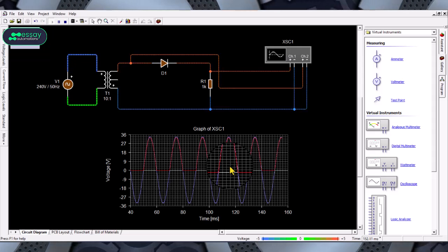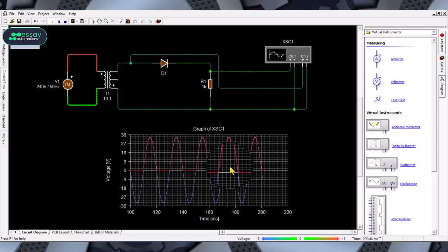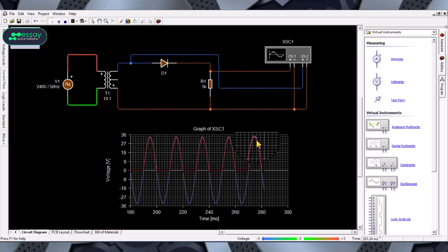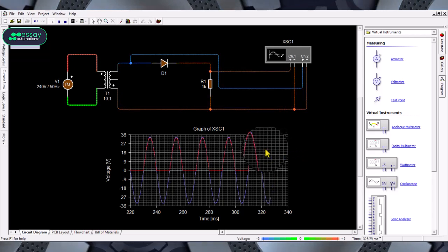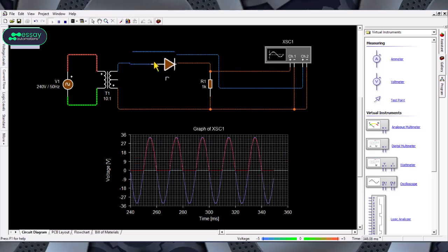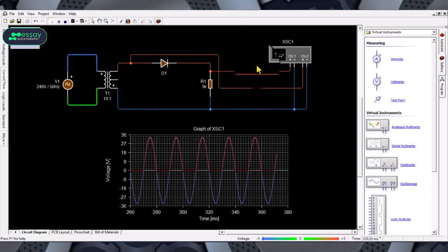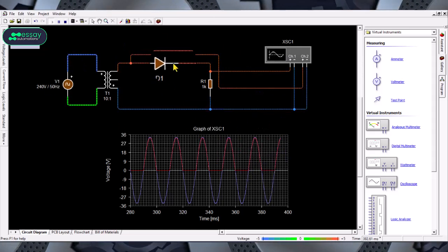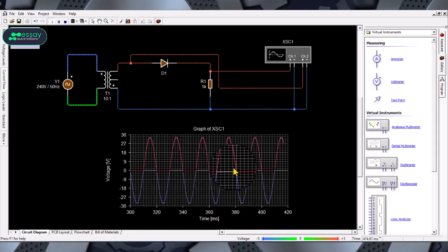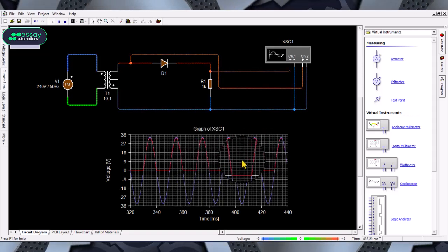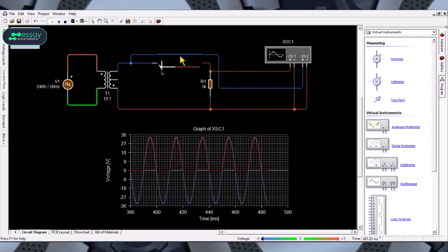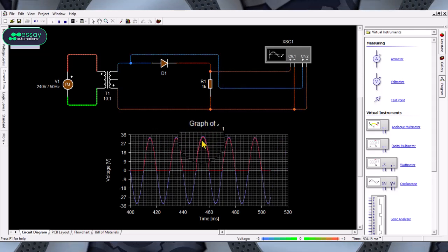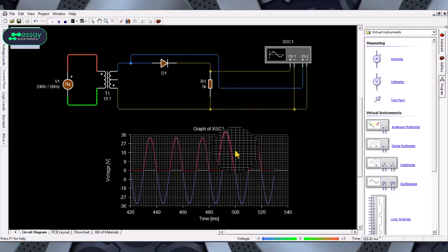As we can see, now the blue lines which are going up and down is the AC form of this circuit, and the red lines is the DC waveform of this circuit. The output, that's the red, is pulsating. This is typical of a half-wave rectifier. This is because the diode conducts during only the positive half cycle of the AC. That's the blue one. We can filter and use a voltage regulator to get a more DC-like output. I'll try and demonstrate this in my